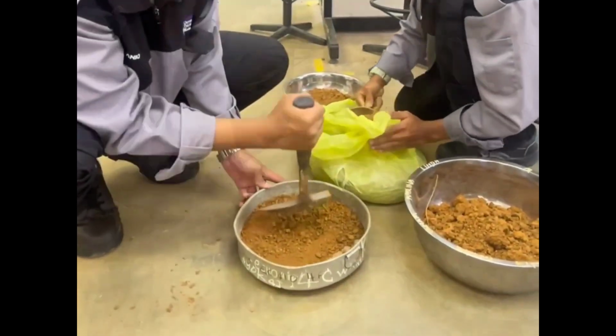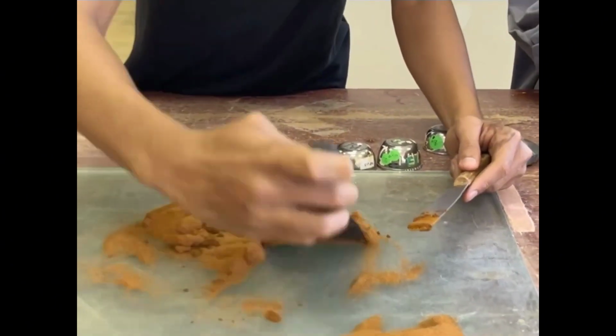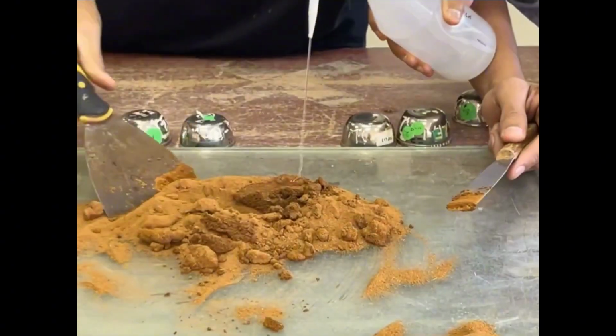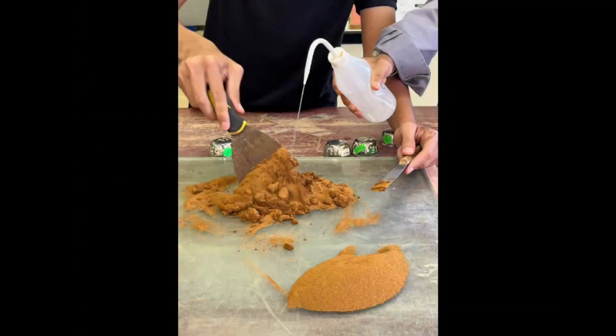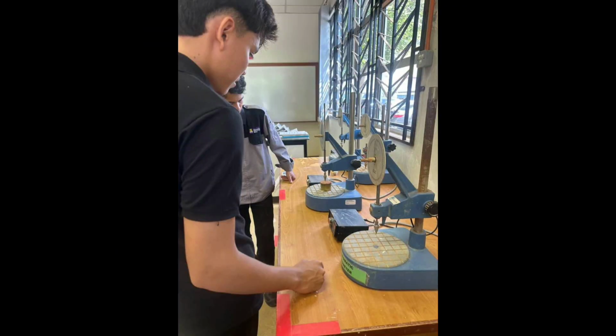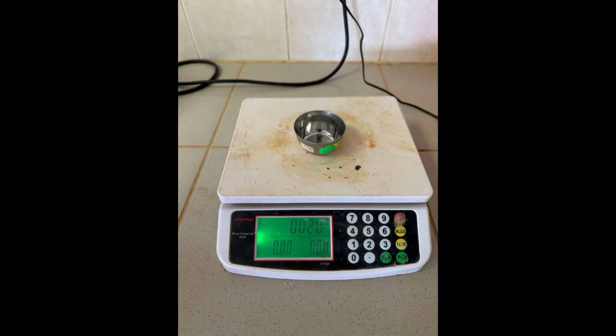For the liquid limit test, a soil sample of 300 grams passing the 0.425 mm sieve was taken, and then we add distilled water and mix until a homogeneous paste was formed. The soil paste was transferred into the cylinder cup, avoiding air entrapment, and the surface was leveled. Next, the cone was lowered until it just touched the soil surface and the initial dial gauge reading was recorded. The cone was released for 5 seconds and the penetration depth was recorded.